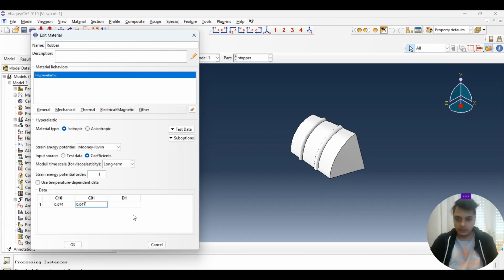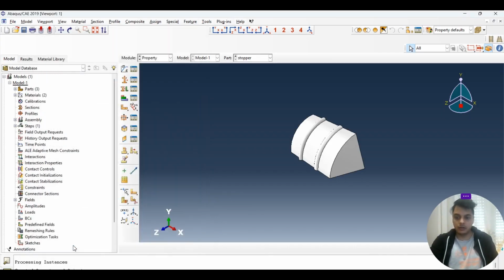Make sure that this type of hyperelastic material has a different theory, and one has to really understand this theory, so that you know what the different parameters being added here are, and what the constitutive laws and equations are that define this. For example, if we talk about soft tissue biomimicry, then we have the Ogden model. So we have to understand all these parameters that we put, like alpha 1, alpha 2, and even compressibility factors. So everything is there.